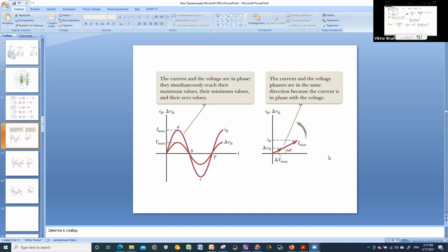And now next, what we need to discuss is so-called RMS current, which stands for root mean square, which gives us an opportunity to link the rules for alternating current circuit and DC current circuit in order to describe them with similar equations.